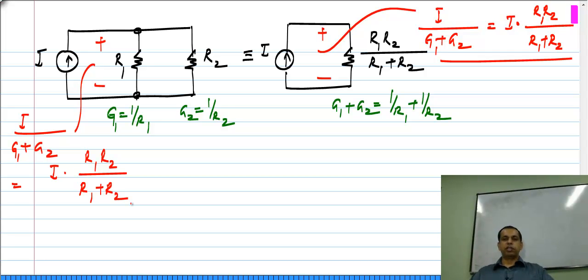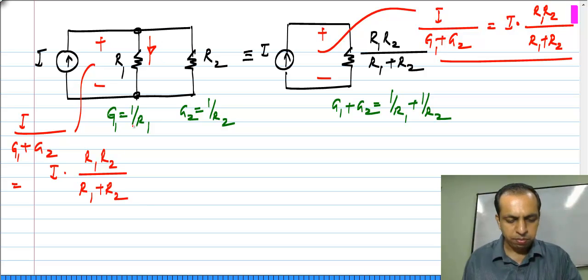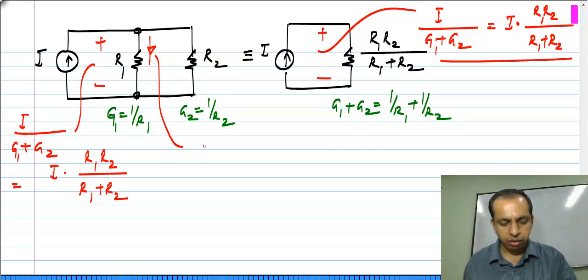Now, you may be asked for this voltage, in which case we have already solved for it, or you could be asked for currents in individual resistors. So, this current is nothing but the voltage across this resistance divided by the resistance, or the voltage across this resistance times the conductance value. Okay. I will write it in both forms.